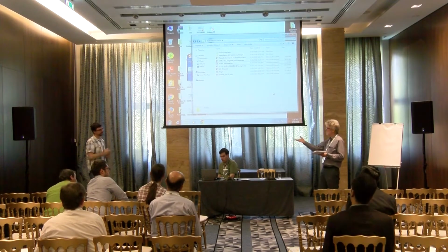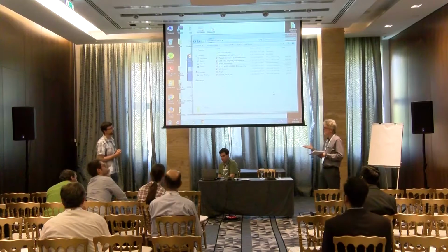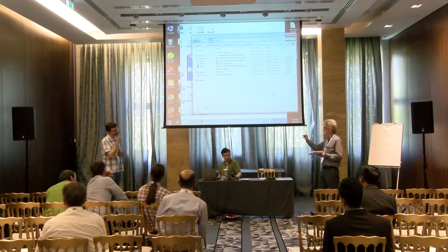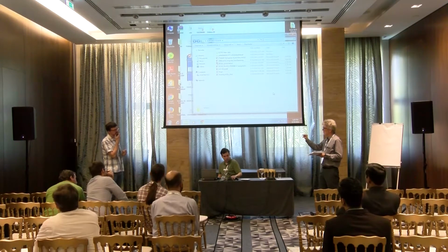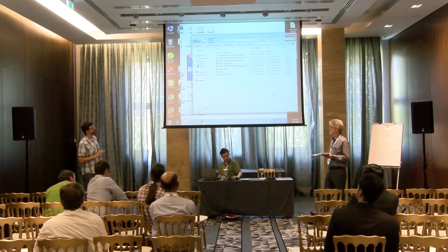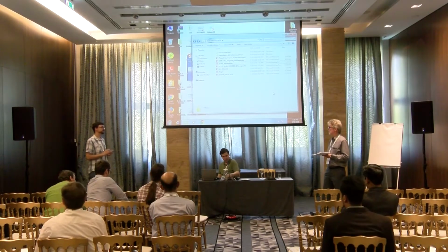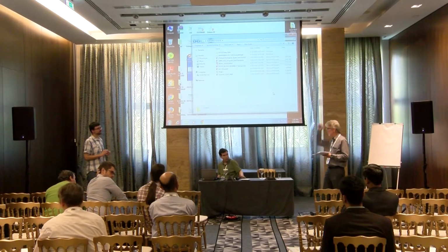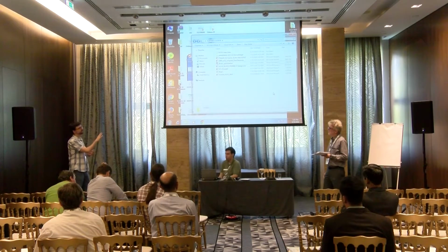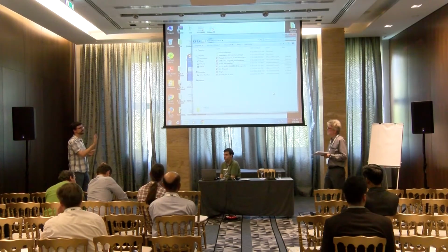But you have now different experimental results on the wear resistance, but doesn't that depend on the thickness of the graphene? Thickness is theoretically 3.4 angstrom, so 0.3 nanometers, if you have only a single layer. And you did have only a single layer? Yeah, here I consider single and bilayer, and when I consider thicker graphene, it is 4 to 5 nanometers, let's say around 10 layers.